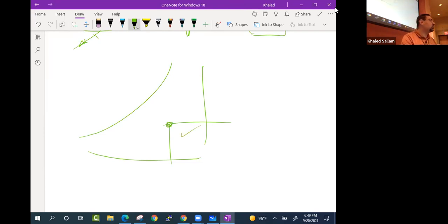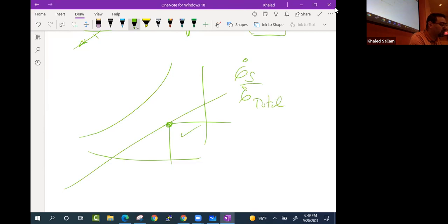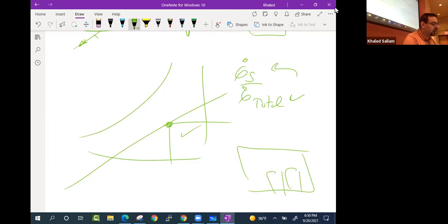Okay, now the second question is, you said that we know the slope. We know the Q dot S over Q dot L or Q dot S over Q dot total. How do you get that ratio? Well, when you are designing the system, you can design the system for a certain load. So you are saying, well, I have an office space, and that office space will have two PCs, and there will be two guys working in that room.